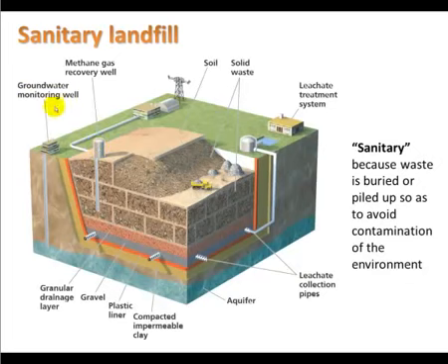And then ultimately, what we hope to do is cover up our solid waste with soil. Actually, that is what we do. Each day they put a layer of waste and then cover it with some soil, and then the next day put more waste, then cover it with soil. So you can see here how this structure is set up with layers of solid waste separated by layers of soil.